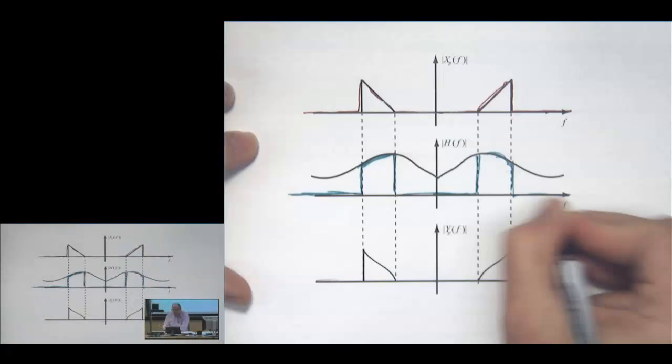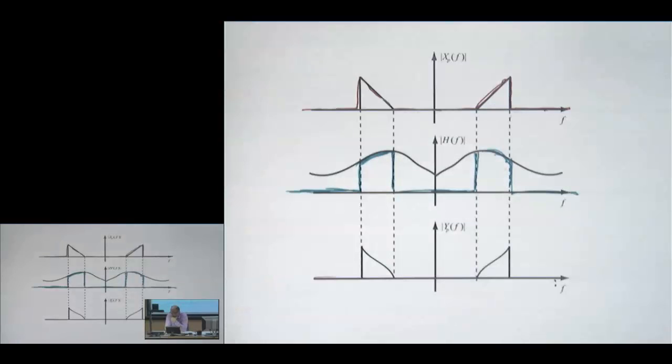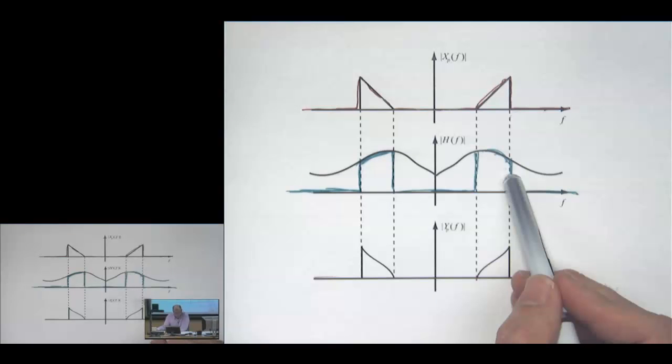And this argument is a bit similar to when we derived the discrete time equivalent of a continuous time impulse response. There was a similar argument in there that if we band limited it, that's all we care about. So this is the same argument happening here, except we're applying this to a passband signal. Now, what I'm going to do is show you the calculations that are going to let us first compute this and then find that baseband equivalent.